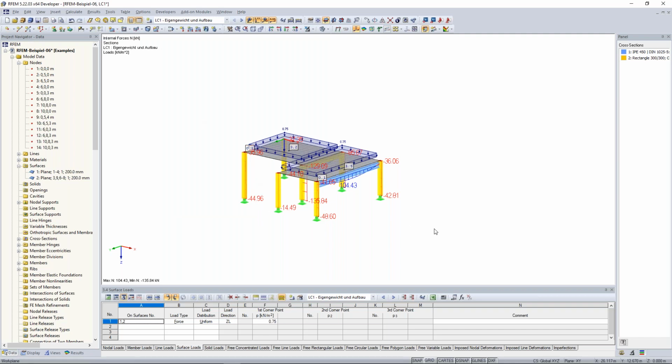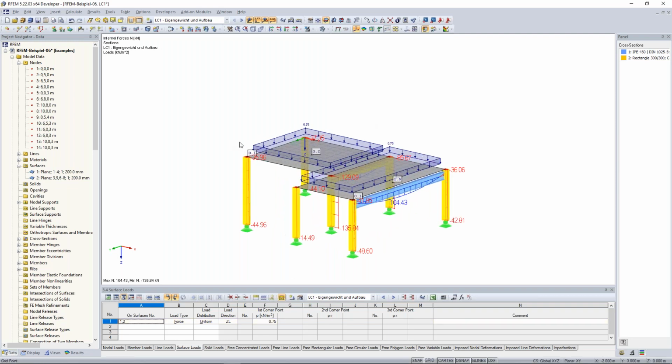When I do this from the other side, so I begin from the right side to the left side, everything which is concerned in this selection window, everything within there is also going to be selected. So in this case, it would be the column and also the downstem beam and also the surface. Yeah, this is important to know, the difference. So from left to the right bottom, I select just what is in this selection window, and from right to the upper left corner, I select everything which touches this. Yeah, note the difference.